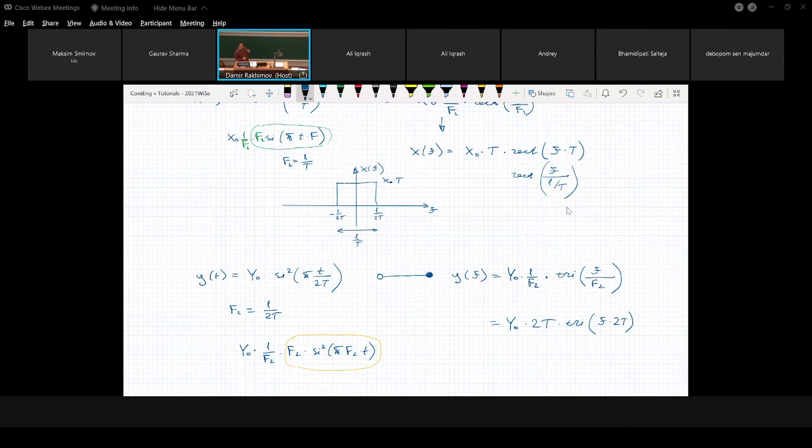And what you do, you perform additional conversion steps, but in the digital domain. This is what we're going to show you: we have a so-called intermediate frequency, and we perform this transformation, now we're talking about the transmitter side, in the digital domain. So we select any intermediate frequency we want to get, and then we upconvert our signal to this intermediate frequency. And then at the second step, we add the carrier frequency by multiplying by cosine. I think it's correct. It should be delta f.